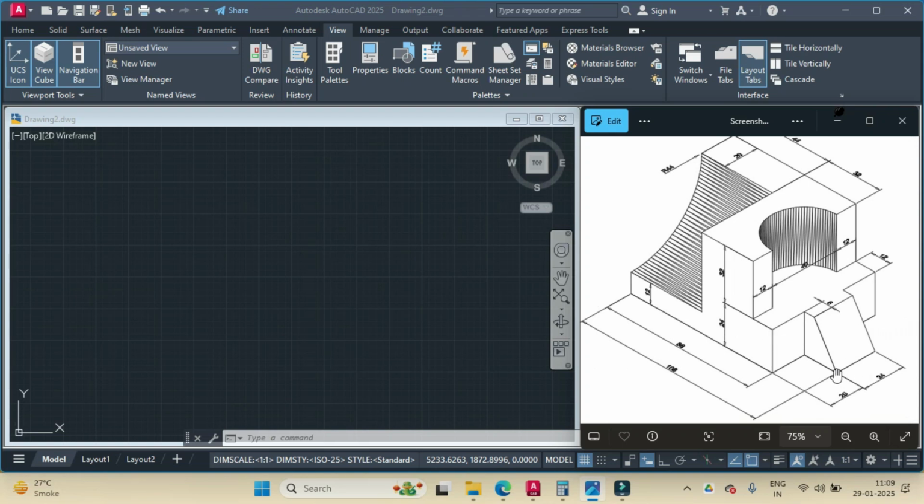Then I would draw one line from here to here, and this point would be 20 minus 6, that is 14 units. And then using press pull I would cut this plane so that we get this particular surface. Then on the back of the geometry I'll click over here and I'll draw a circle of radius 44 and press pull it to a thickness of 44 and our geometry would be complete. So let me show you how we'll proceed with the drafting.